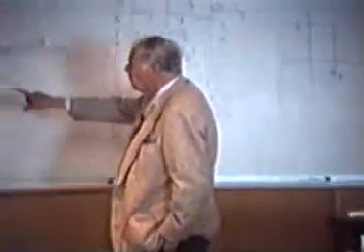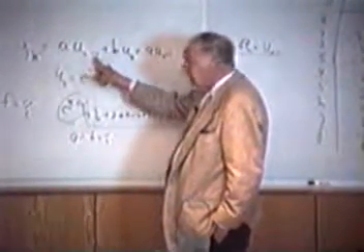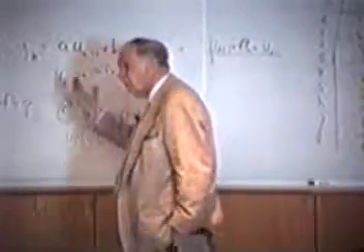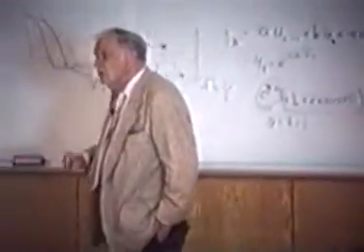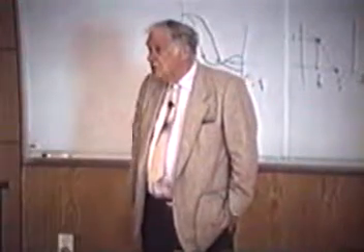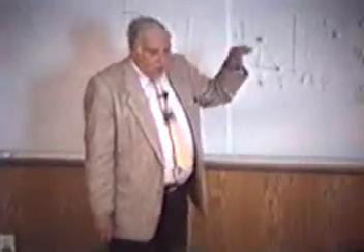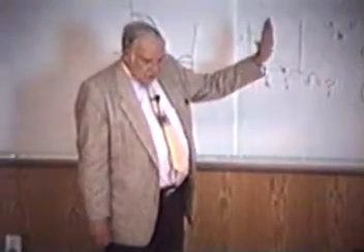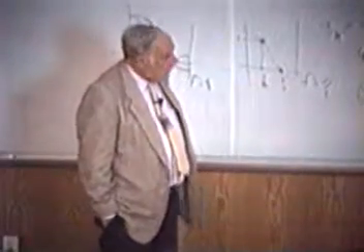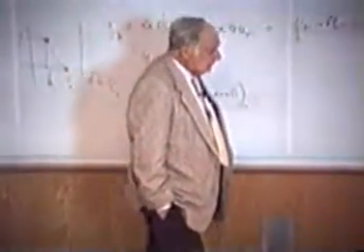Now what we're going to do is observe the obvious. When I had a symmetric filter, these two terms, when I factored out the e to the n, I would have a negative and a positive, so I'll get a cosine. If there's another term out here and here, I'll have a cosine of 2. The expansion will be in terms of cosines. If I have an odd function, it'll be in terms of sines. For example, a differentiator. Smoothing filters being symmetric will always give you sums of cosines. Differentiators, which are odd, will give me sines with an imaginary coefficient, but it'll take care of itself in time. So my problem is, how will I get it done?